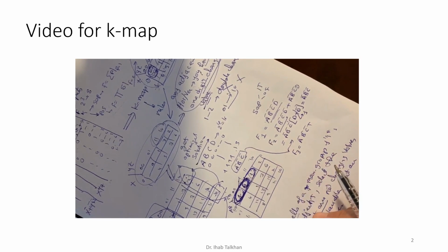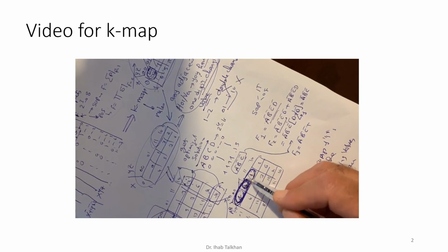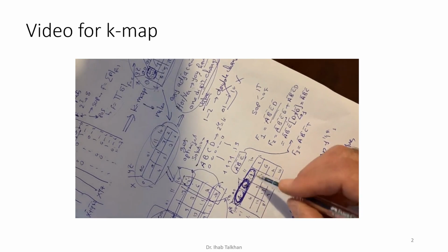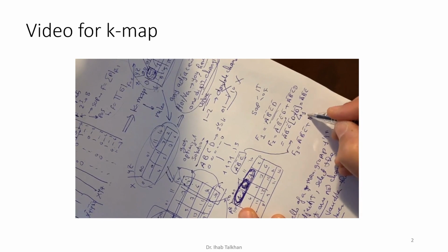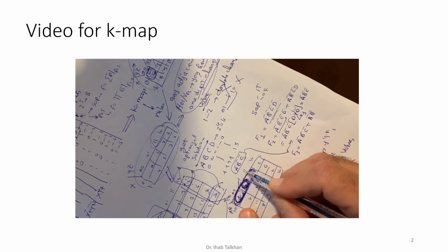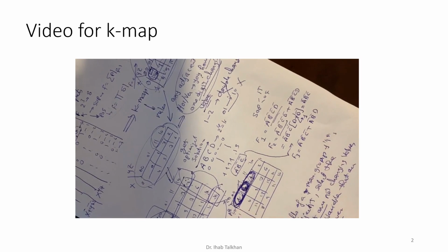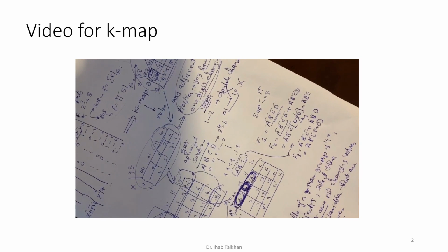As you can see here, the K-map gave you another advantage: you can have overlap. Overlap means you can use this one with this group, and use the same one again with the other group. So this is actually an advantage of the K-map. This group gives A bar, B bar, which are not changing values. C is changing value this time, so C is out, and you have D. So this would be the equation for FC, which at the end equals A bar, B bar multiplied by C bar, plus D. At the end you have this type of equation.